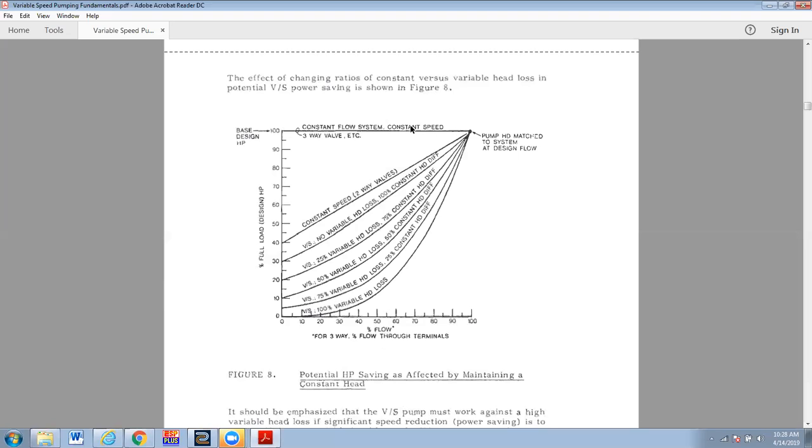And the pressure drop is, if you're 50% flow through the coil, 50% through the bypass, you do have a reduction in pressure. But he's ignoring that in this discussion. And he's saying that no matter where we are. So, if the thing was snapping back and forth between the coil and the bypass, then this would be 100% true. But anyway, for the argument, that's where we are. And so what we see is, so VS equals 100%.